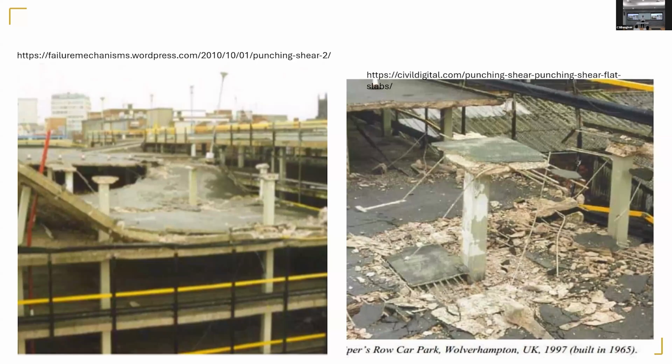And this was one of those cases where the contractor did not follow the rules, and they actually put 3 to 4 times more load on the slab than they were supposed to. So this happened not only in my project, it was happening all over the world, right? And if you search now for punching shear failure, you will find hundreds of pictures. So the codes started to realize that this is not good. So now what they've done, in the most recent codes, recent means 10, 15 years ago, they ask you to put bottom reinforcement at the bottom in such a way that if it fails down, the whole slab can hang from the columns.